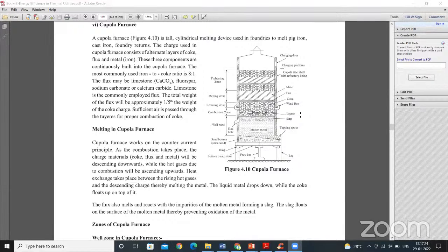Initially the temperature is going to be minimum, and when the metal is poured inside the chamber, which is called the crucible, they will increase the temperature. Then automatically a thyristor controlled panel is definitely required. Because of that, the harmonics produced are also very high. We have measured the harmonic level of many foundry industries.